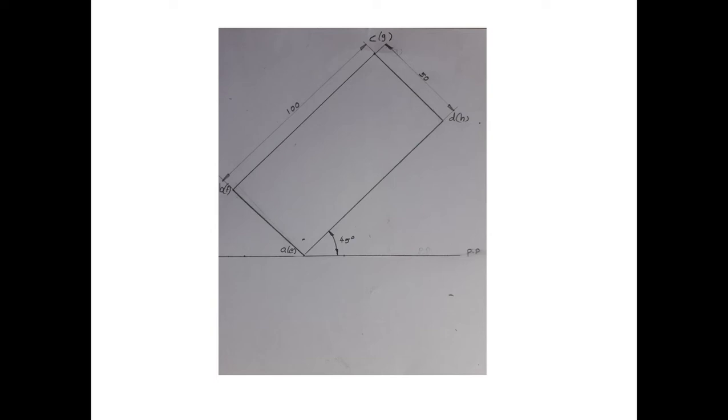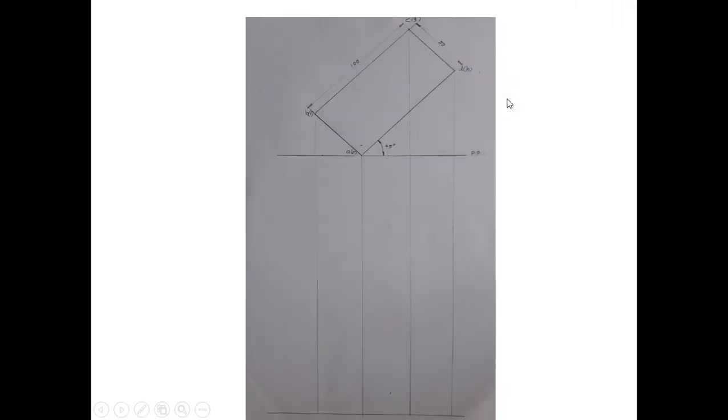Those points will be inside the bracket, and also the face EFGH is the face on which it is lying on the ground. So this is the top view of the object with respect to the picture plane. This corner is touching the picture plane. Then just do one thing. To show the ground line, you just draw a line like this. Then drop all the points to that line. You need maximum space between these two, so you do one thing.